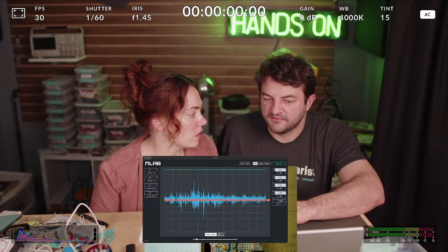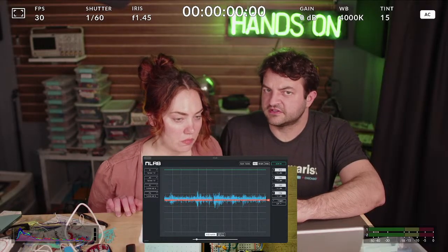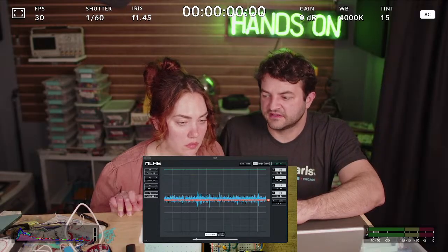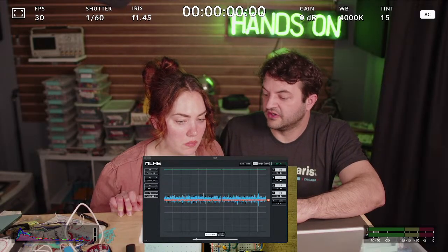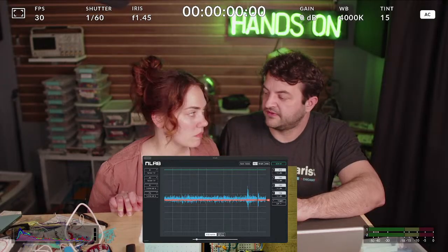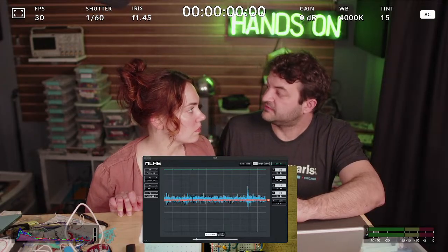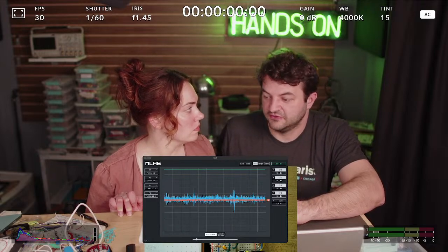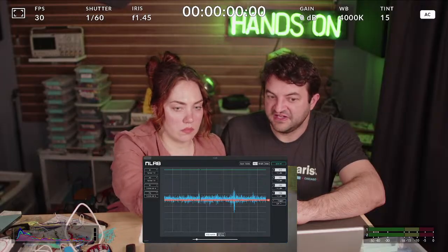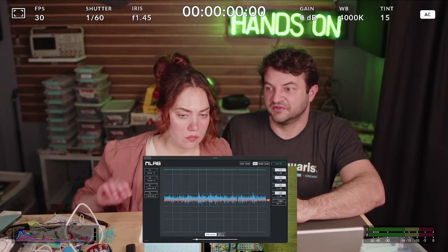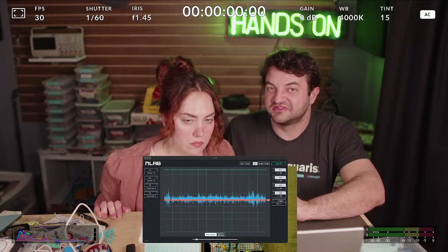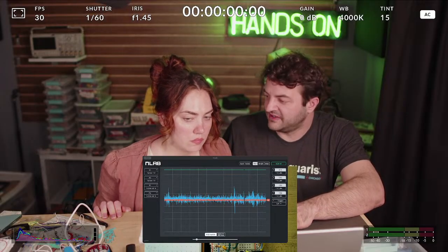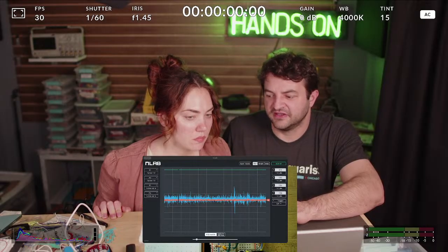Right. So if you have a specific application you're going to use, let's say you're building a voltage regulator or an audio amplifier, the PDFs, the spec sheets, actually usually recommend the type. So that would be your first clue. The data sheet for the thing you're trying to build says what to use. I would always follow that. Sometimes they'll give you the exact part number to buy on DigiKey as well. But if you don't have that, then you're basing it more on the size of the capacitor.